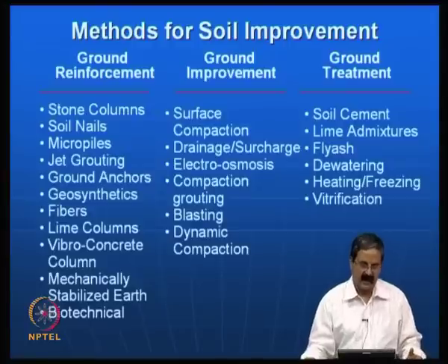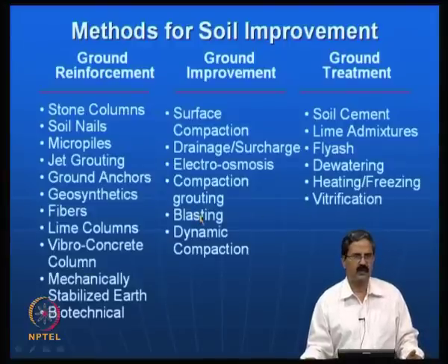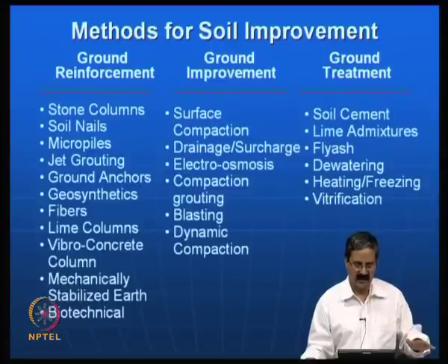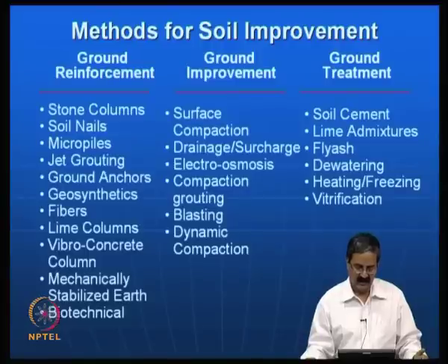I have seen some cases, in fact, where you place mines, like when you want to break rocks, you do blasting, right. Similar to that, you introduce some charges into the liquefiable deposits and then blast them. What happens? Because of the energy that is there, the whole soil gets consolidated or compacted in a very short time. So, blasting is another technique people have used. In fact, in liquefaction problems, this is one of the techniques that has been experimented with a great deal, because it is a very useful technique and simple to use.